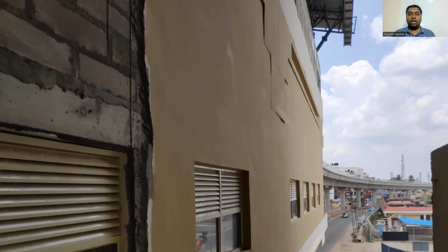So in a metro station, it is very important for us to understand the components of a metro station. In ground level, we'll have the pump room. And when you go up, the generator room is sometimes in the ground level or sometimes in the concourse level, depending on the different design. In one station, we had it in the concourse because of the traffic problem below, because it's Bangalore at the end of the day. Apart from that, the majority of our stations had the pump room and diesel generator room in the ground level itself. And then in the concourse, I showed the plan.